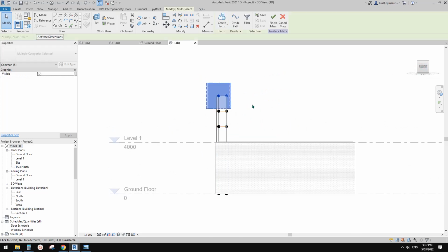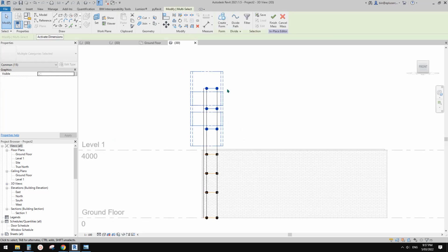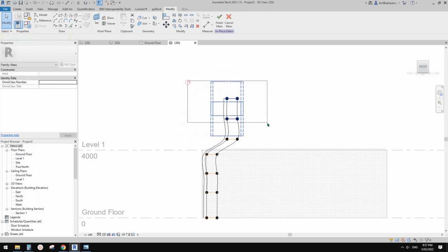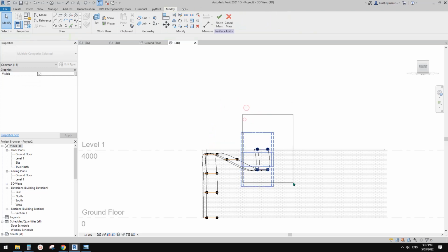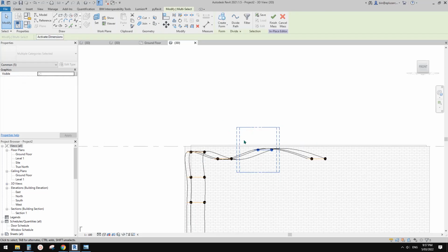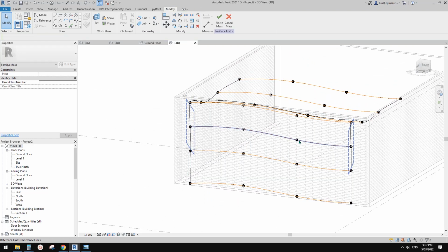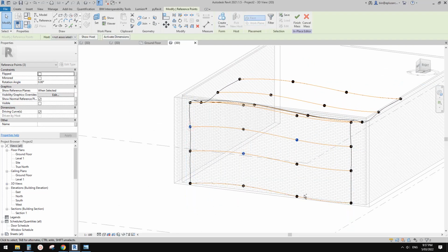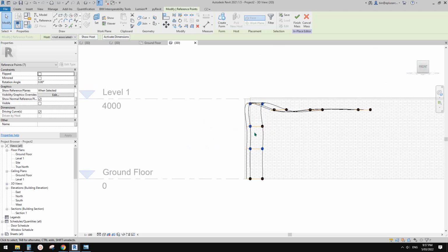So now we can select, let me change it to wireframe, WF, and we can select these and use your keyboard to adjust them. Okay, so it's very easy. You can just adjust the reference lines altogether, or you can also adjust individual points. For example, you can select multiple points there, here, this one, that one, this one. Okay, so go to side view, and you can just use your keyboard to move them.